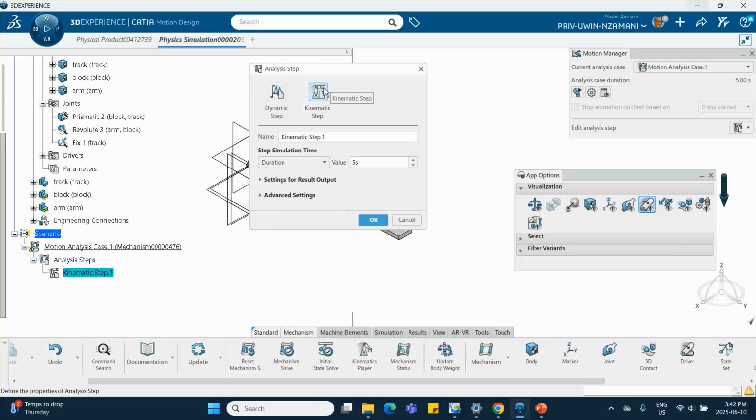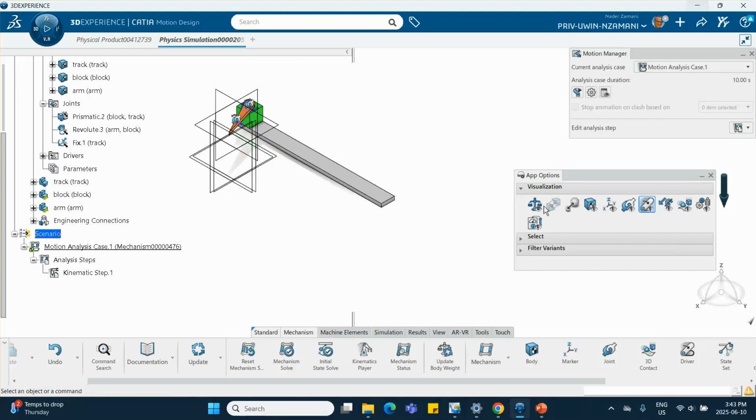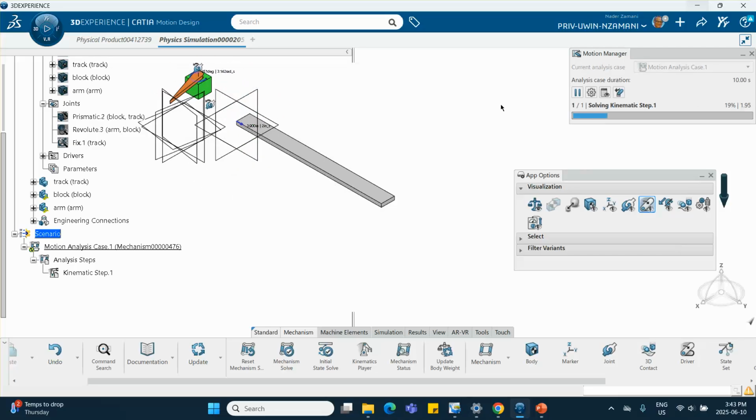So I select this, and I want to go over a 10-second interval, and I want to extract position, velocity, and acceleration. You say okay. Okay, you can preview it, and if it goes in the wrong direction, we may have to go and fix the scale by putting a negative sign. So let me preview it first. This is not running it, just previewing it. You see, it's going in the wrong direction. So we go back.